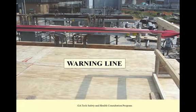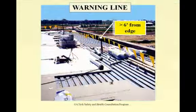A warning line is a barrier device used to alert workers they are approaching an area on a roof with an unprotected edge. They are to be used only when a fall protection system is infeasible or impractical, and access to the area beyond the warning line should be blocked when no work is taking place. Here is another example of a warning line. Note the high visibility flags. The warning line should be no less than 6 feet from the roof edge.